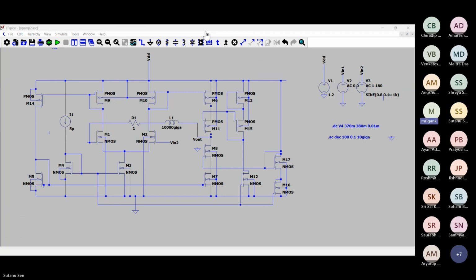And here 300K gain was coming, which is also a little surprising. I was not expecting this kind of gain. I was expecting maybe something of the order of 10K, something like 30K, 40K, but it is 300K. So we have some margin. We can reduce the gain by a factor of 10x, and then also we will have good enough resolution.